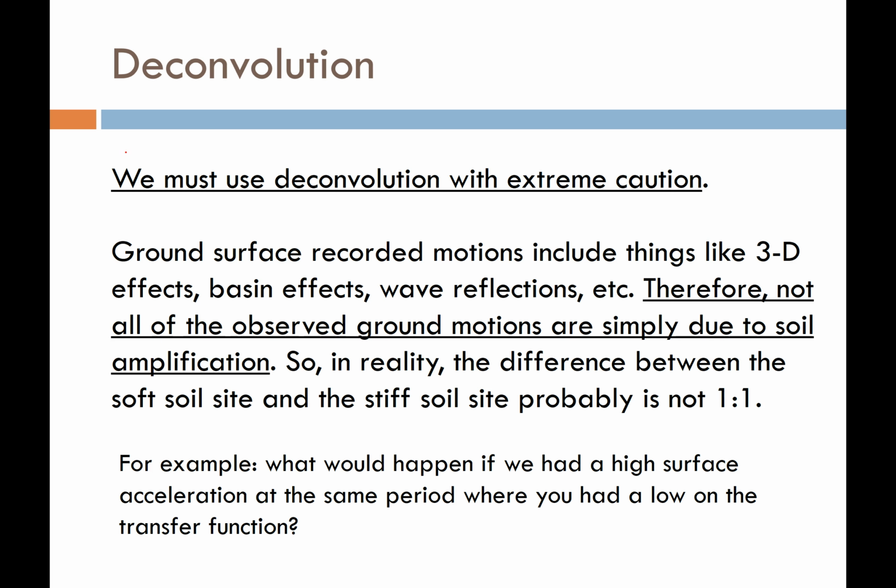Here's the thing. You have to be careful when we use deconvolution, because there's a lot of different things going on in the soil, like large strain effects, resonant frequencies, basin effects, and reflections of waves that aren't modeled necessarily in the linear response analysis, but are going to come through as potentially spurious resonances.